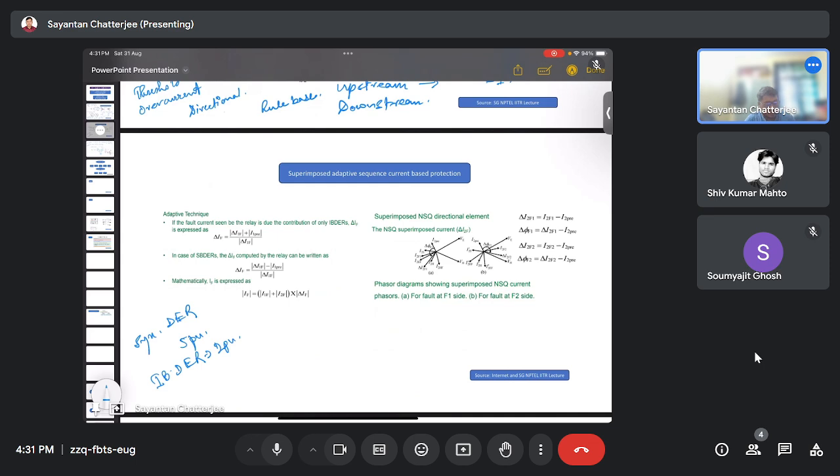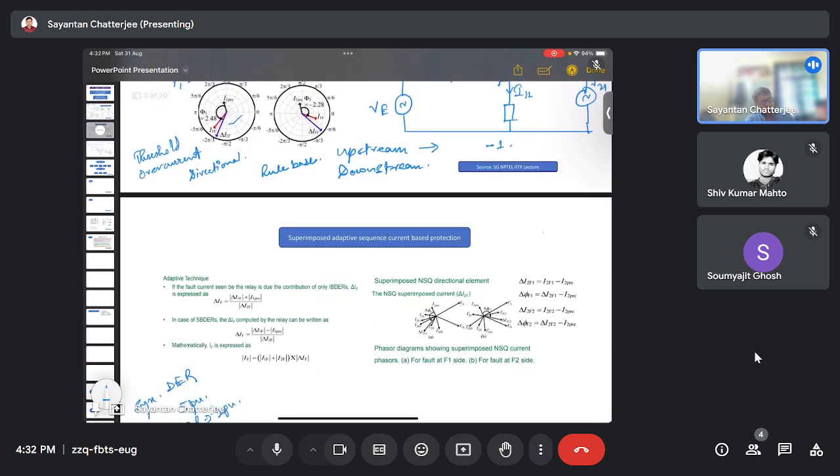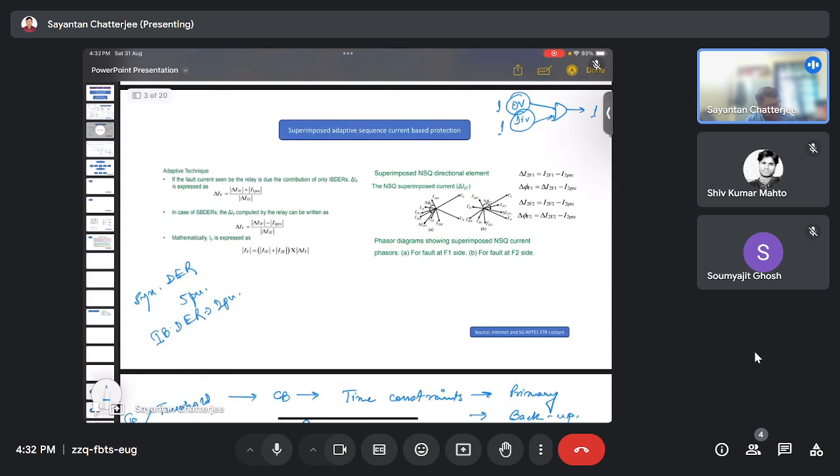So before that, the decision that was previously given by both the units has to be merged. Okay, so in that merged application, we can see that if we put the overcurrent and the directional together in an AND gate, and out of this AND gate, if both of them become 1 and 1, logic becomes 1, then only we'll have 1. Otherwise the thing won't operate. Okay, so both the overcurrent relay as well as the directional relay have to send the trip command, the signal.